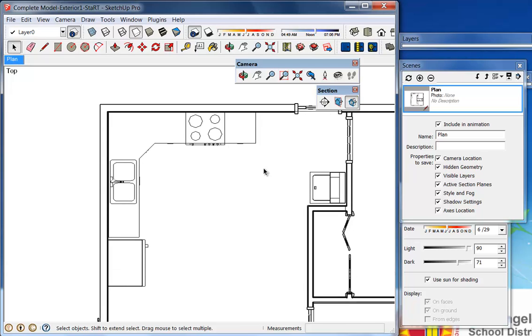But I could also import the regular floor plan view using layout and zoom in and crop my view there as well. So it's not really necessary to get any more detailed views here unless it's very different from the view I have here. And that could be what layer information I have on or off, or what style I want to use. So let's just continue. Now what we need to do is produce our elevations, right? All of our elevation markers and documentation, all those annotations will be added in layout. But here we want to establish the physical section plane, right? So let's start with the first one.